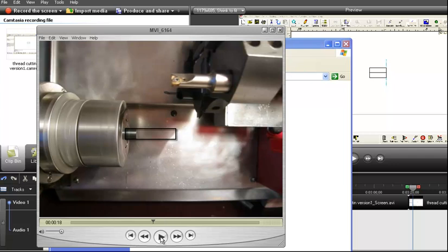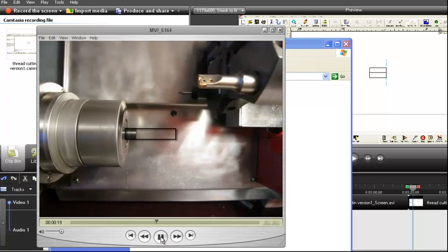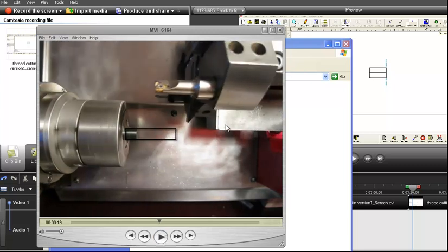So we'll press continue, and from that position the tool went diagonally, with shortest path, from here to my position X10 Z10, and my idea was to use Go 2 to stay here, and after that execute tool change command.